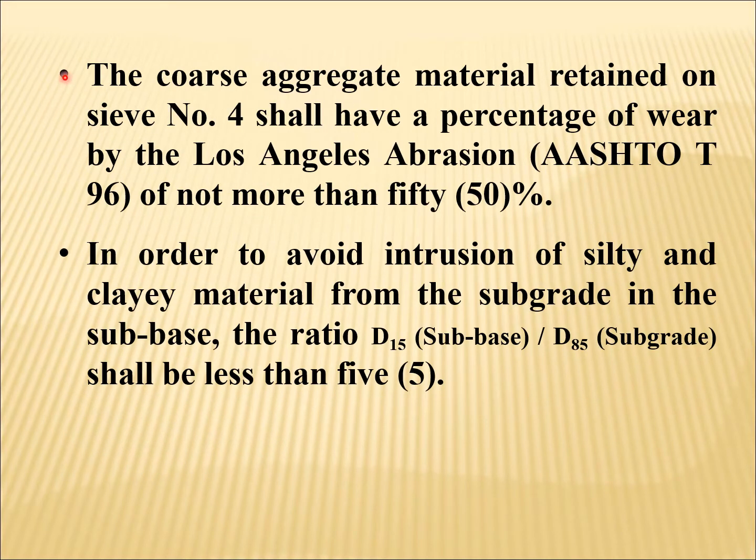The coarse aggregate material retained on sieve number 4 shall have a percentage of wear by the Los Angeles abrasion of not more than 50%. Well, keep this in mind that the smaller the value of Los Angeles abrasion value, the better is the material. So the requirement for the subbase material is that Los Angeles abrasion value should not be more than 50%.